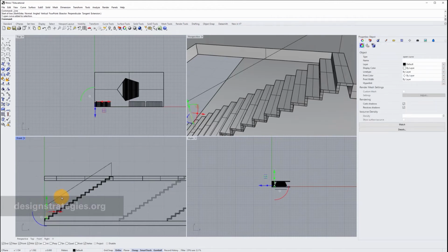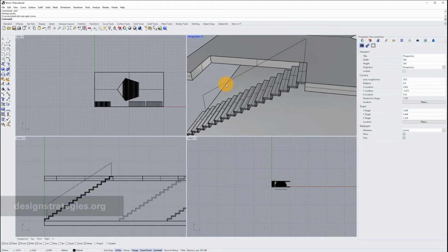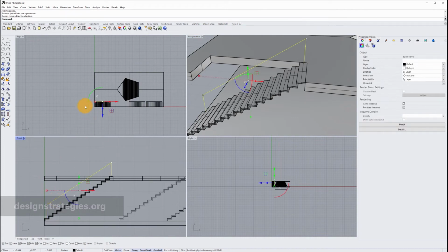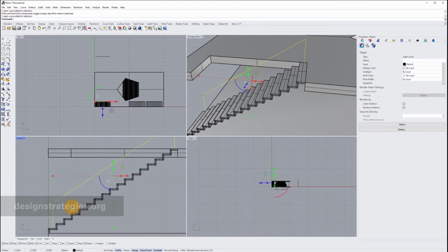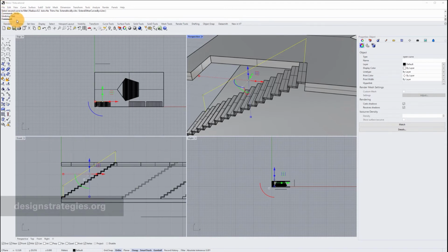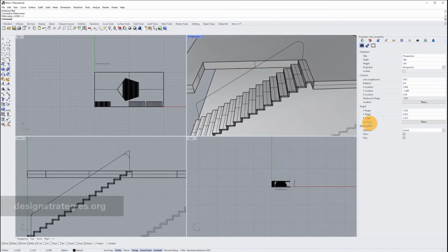I can just select all three lines, and next thing I join them. And starting from this, you have obviously several options. I just copy this once to the back because probably we would like to continue working on this. You can just choose this line, and you can then use the command fillet or fillet corners. If I use fillet corners, then I just have to select the whole line and just say with a radius of 20 centimeters. Somewhere like this. This looks quite good.